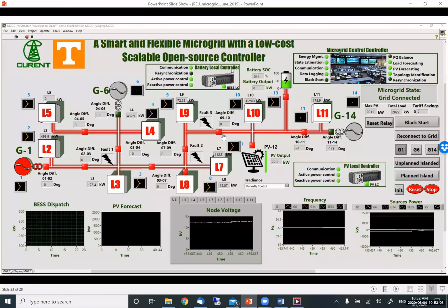Once we pick up one load section, we get an inrush current, but it is under control. And we don't pick up a load section as a whole; we pick up one by one. For example, when we expand the boundary, we pick up this one and this one, one by one, to make sure the disturbance applied to the system is small enough and under control. So you use your nodes to control that.